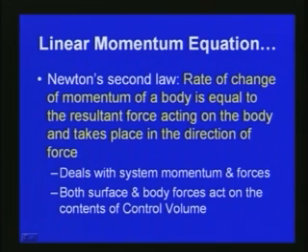As we have already seen the control volume concept, we have to consider both the surface forces as well as the body force acting on the control volume. Most of the problems which we will be solving here use the control volume. For the control volume, we have to consider what happens within the body, the control volume itself, and what happens on the surfaces. So while we consider the linear momentum equation, we are using Newton's second law: force is mass into acceleration, and we are equating that to the momentum changes.